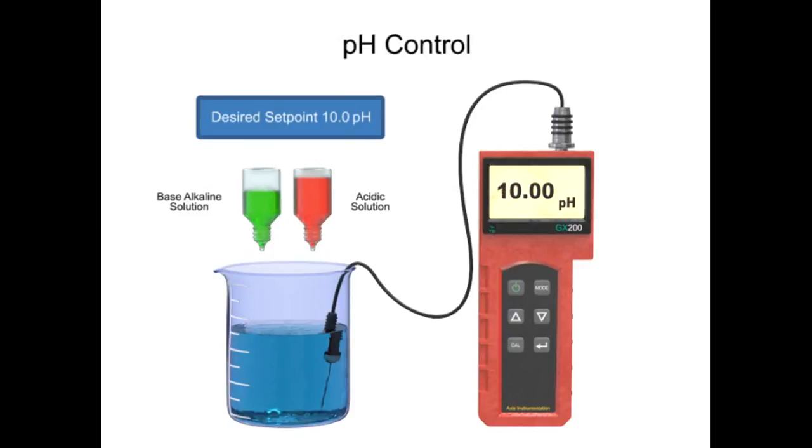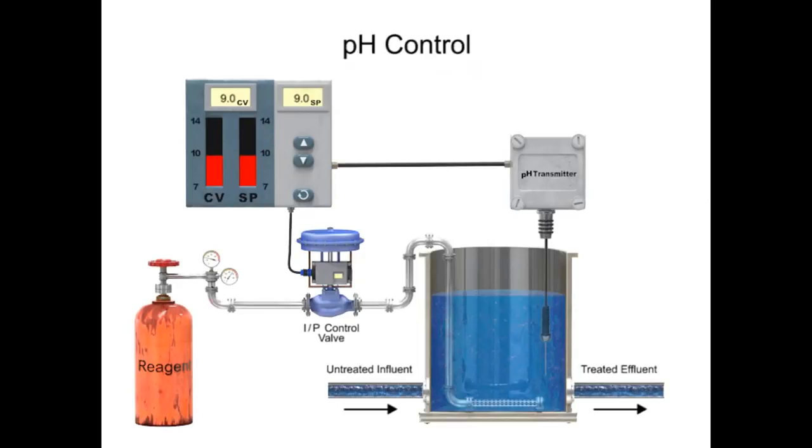When a low alkaline level is detected in the solution, a base is added to increase the pH level. In both cases, the corrective ingredients are called reagents. Accurately applying the correct amount of reagent to an acid or base solution can be challenging due to the logarithmic characteristics of pH reaction in a solution. Implementing a closed-loop control system maintains the pH level within a certain range and minimizes the degree to which the solution becomes acidic or alkaline.